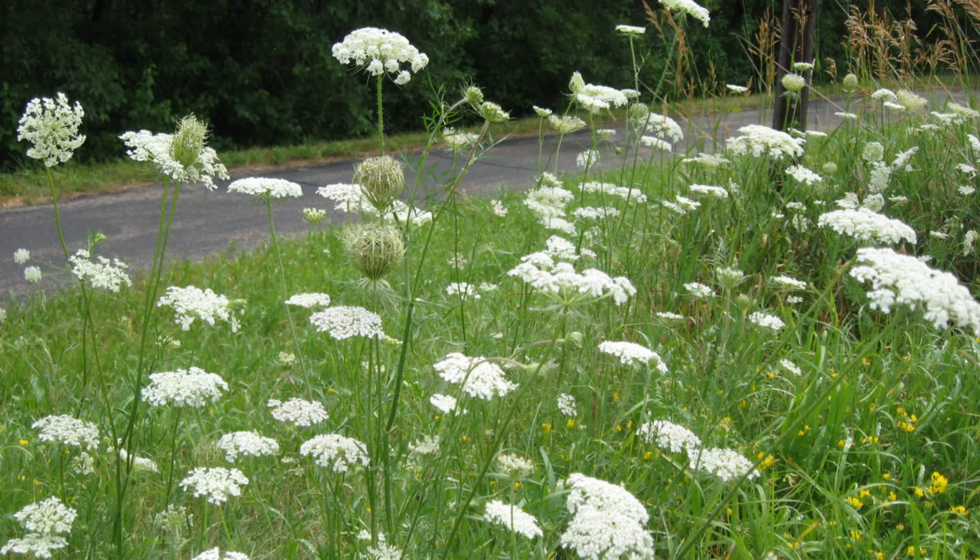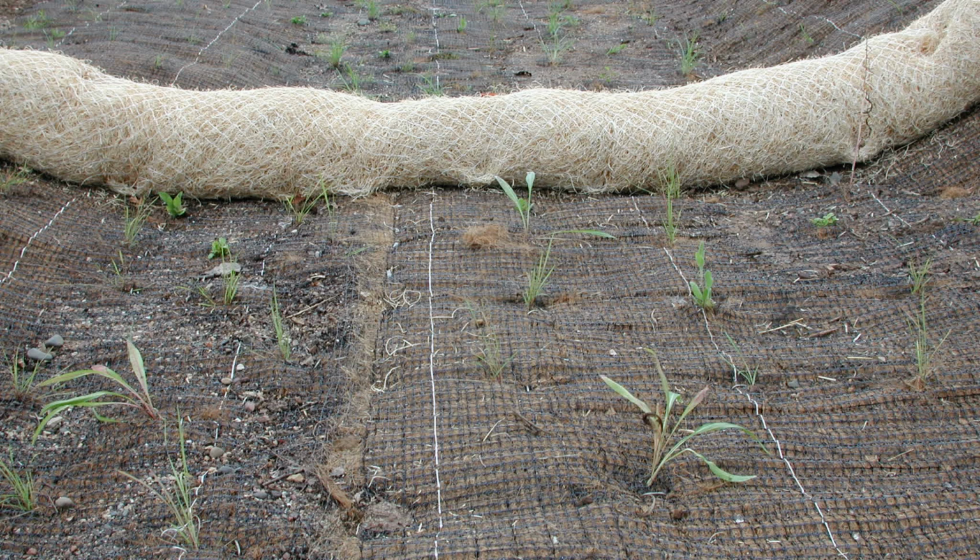To prevent the spread of invasive plants and protect native species, first evaluate each road project to determine if invasive species are present. Always revegetate areas after construction. Clean all equipment thoroughly before mowing a new site, even if it is on the same road. Use certified weed-free landscaping materials, and determine a treatment plan if invasives are encountered.